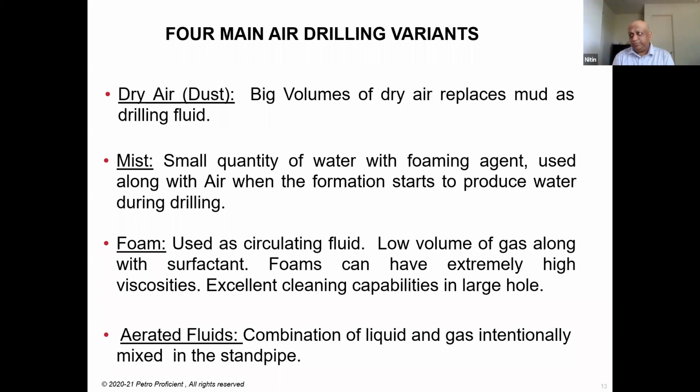And the last variant is aerated fluid. Now, what is aerated fluid? It is basically a combination of liquid, that is your conventional mud, along with gas, normally air. In aerated fluid, you have the entire circulating system as you have on your regular drilling operation, with the difference that you have air being added to the mud system in order to lighten the fluid. We'll see that setup in the coming slides.